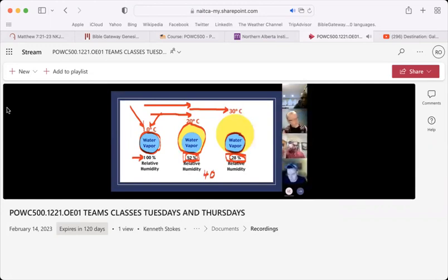Here's a chart on 10-4. It says recommended relative humidity if our outdoor temperature is minus 18, we should shoot for 30. If our outdoor temperature is a little warmer, we're going to shoot for 40 plus. So somewhere between 35 and 45 is a pretty good number.